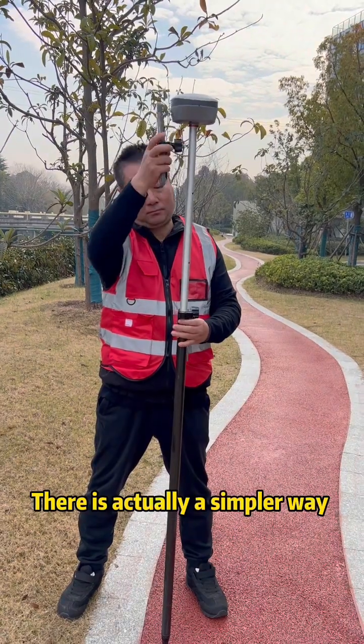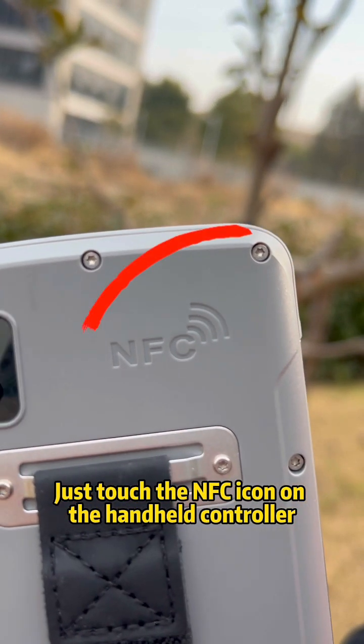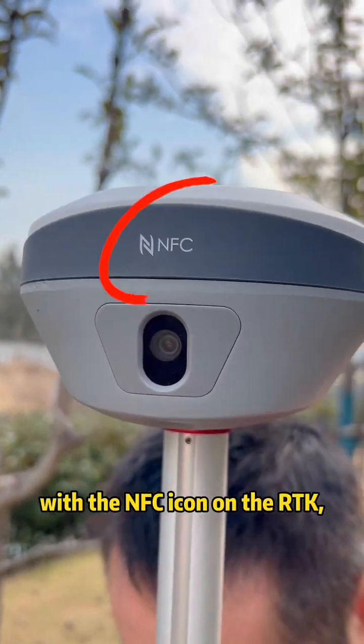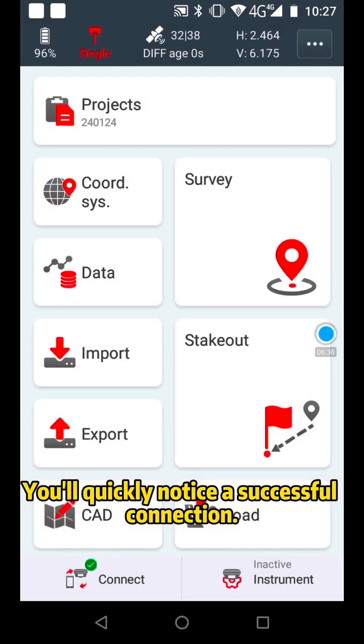There is actually a simpler way to connect the receiver with controller. Just touch the NFC icon on the handheld controller with the NFC icon on the RTK, no additional settings required. You'll quickly notice a successful connection.